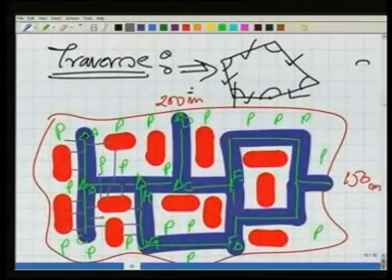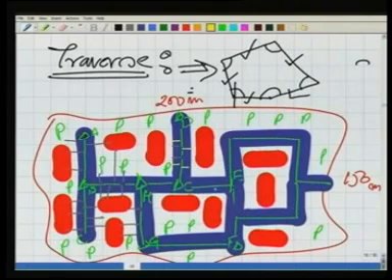So now really the buildings are not obstructing. All the buildings can be plotted. All the trees can be plotted. Also the roads can be plotted. I can take these offsets in the road. Here in the road I can take these offsets to the road. So roads can be also plotted. So using these offsets the entire area can be plotted.